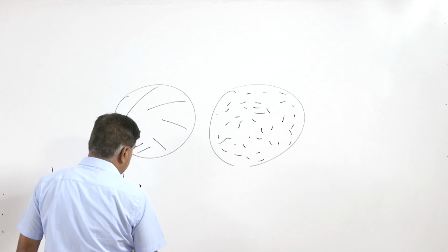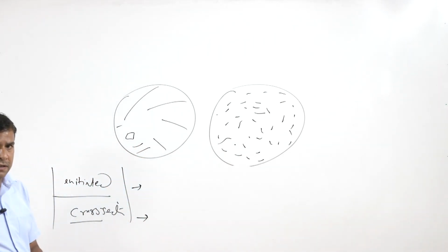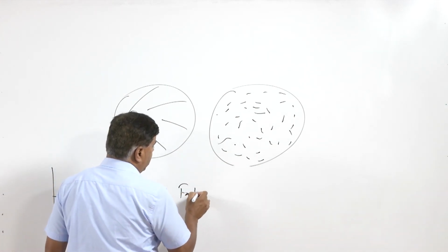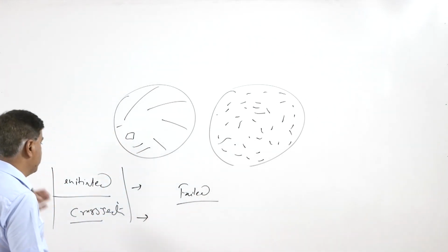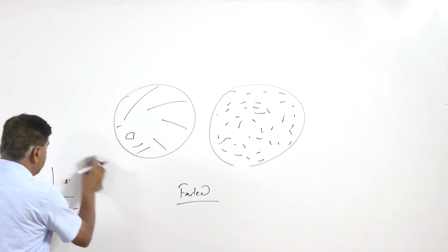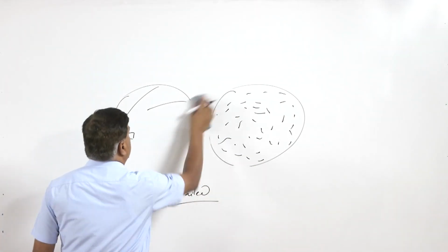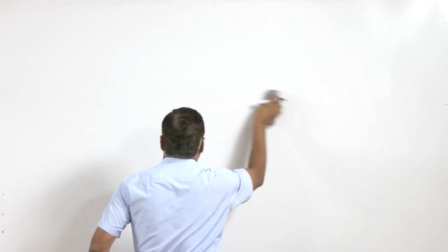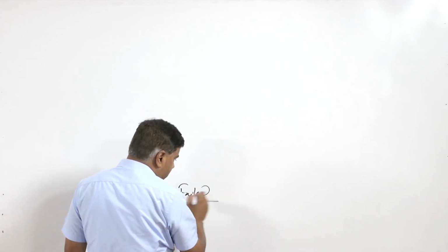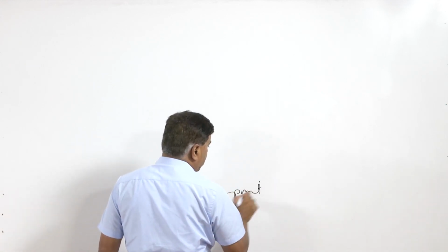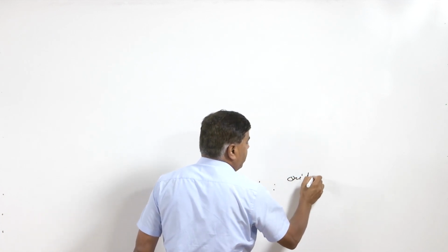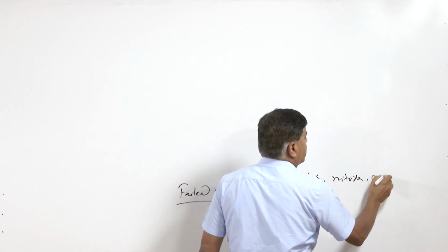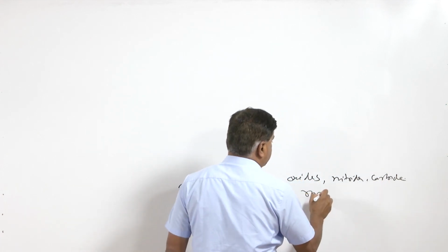Apart from the segregation and distribution of the alloying elements, we also need to see if the failed component has been in service for a longer period, because the service conditions will also have an effect on the surface characteristics of the component, in the form of oxide formation. A failed component after prolonged use can show the presence of surface deposits in the form of oxides, nitrides, carbides, soot formation, rust, etc.